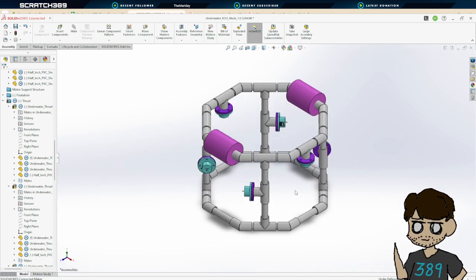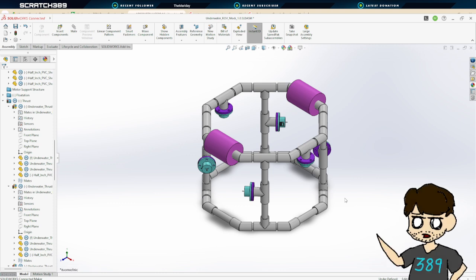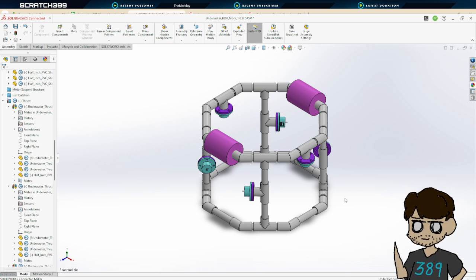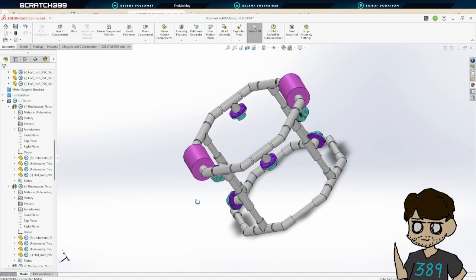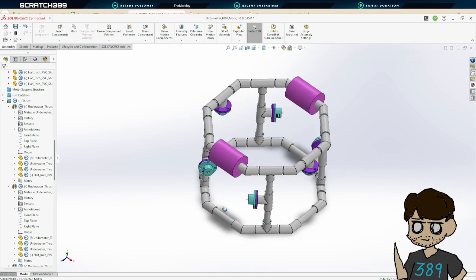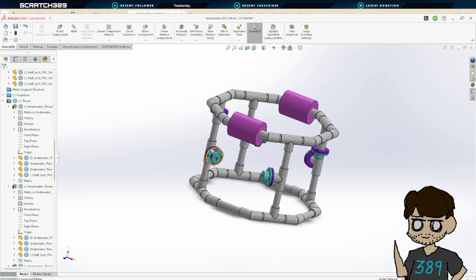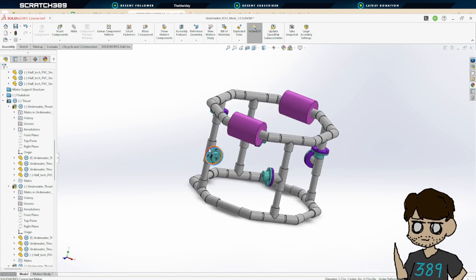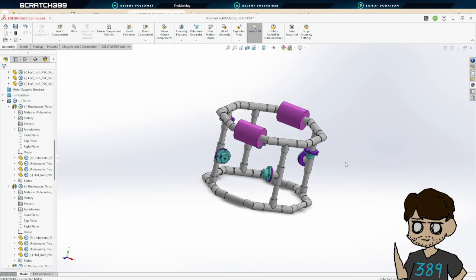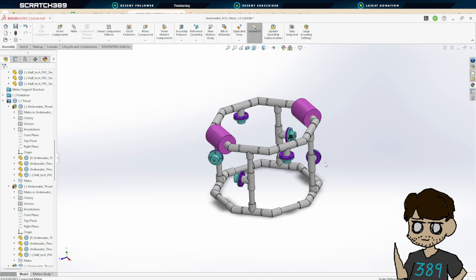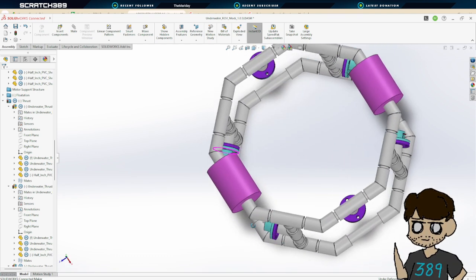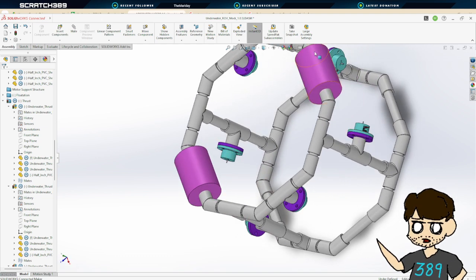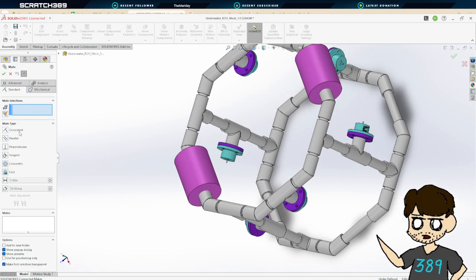Is this the front? I can't tell. I mean, doesn't matter too much, but okay. So this would be how this is mounted, and these could be rotated. I made them their own assembly, so it's not going to show, but you can rotate. So I make these two parallel and then those two parallel. So let's see. Mate, parallel.